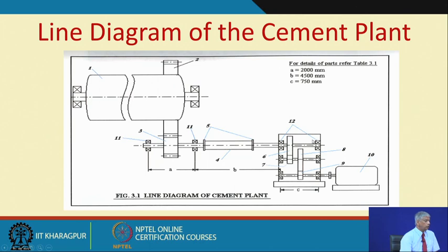So, if I want to do CBM on this gearbox, I have to capture the signal from an accelerometer put on this bearing in the gearbox, and the output shaft of the gearbox connects to a torsion shaft. Okay, and the torsion shaft is a weak structural member in the entire system. So, if it breaks, it will fail here, and it can be replaced and so on.